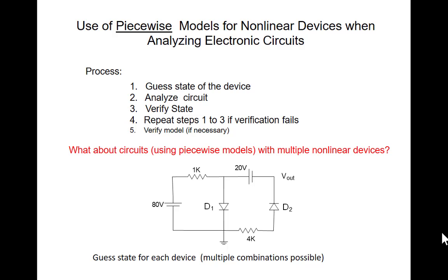Okay. So now we know what different states can exist. Now in any of those 4 states, the circuit's going to be linear, right? Because we're going to put in a piecewise linear model of the device. So can somebody suggest a strategy? Guess a state, solve the circuit, and then verify that state is valid. That is, verify the condition on both diodes is what you guessed. If you guess wrong, the state won't validate. And that just means you have to guess again. So we won't make a mistake solving the problem, but if you guess wrong, it may take you longer to get to the solution.